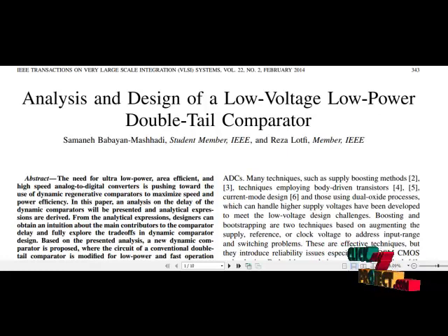The disadvantage, on the other hand, is that due to several stacked transistors, a sufficiently high supply voltage is needed for a proper delay time in existing designs. Another important drawback of this structure is that there is only one current path via the tail transistor. That's what we are going for, a double tail transistor.